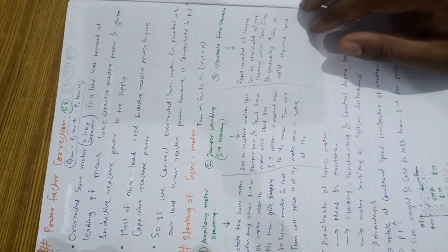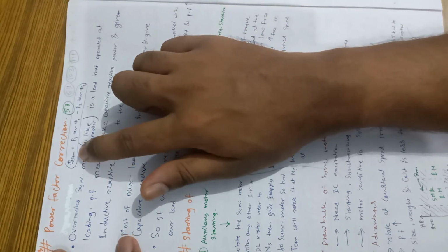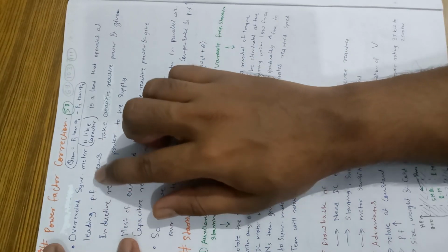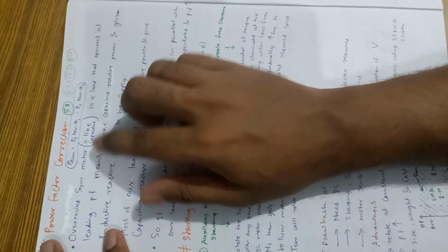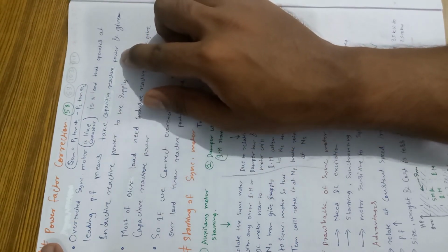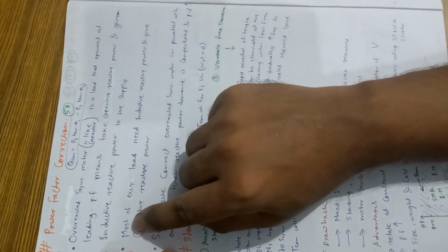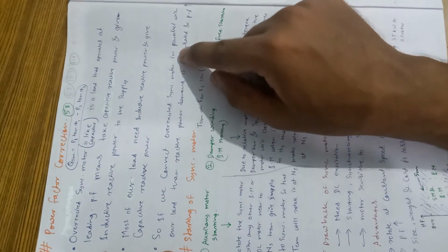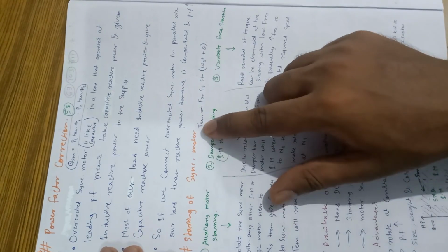So now at last we will study power factor correction. For power factor correction, keep this formula in mind: QSM equals P1 tan phi 1 minus P2 tan phi 2. For power factor correction, the over-excited synchronous motor is the most important. An over-excited synchronous motor is like a capacitor. It is a load that operates at leading power factor, meaning it will take capacitive reactive power and give inductive reactive power to the supply, and we know that most of our load needs inductive reactive power. So if we connect an over-excited synchronous motor in parallel with our load, then reactive power demand is compensated and power factor is improved.